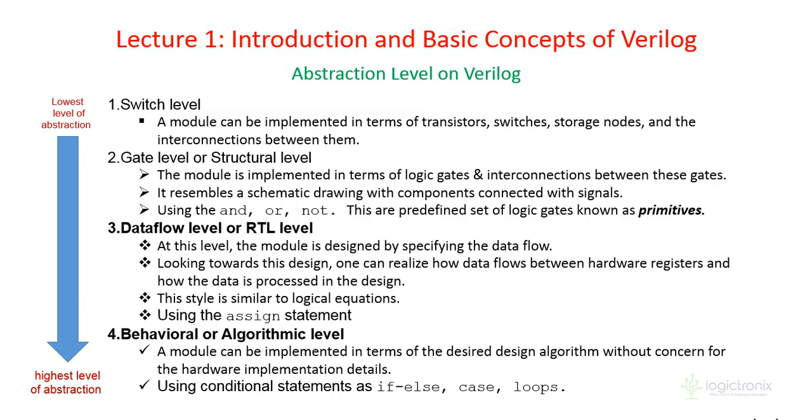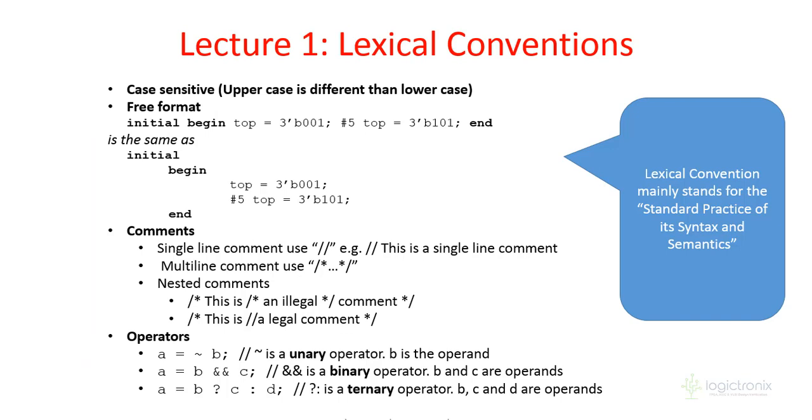Here we have the lexical conventions. As we already discussed, lexical conventions are the standard practice of writing Verilog syntax or semantics. Verilog is case sensitive, so an uppercase variable name is different from lowercase, and if we define a variable in uppercase, we have to use that same name and style. Another point is how we write the code, multi-line or single line.